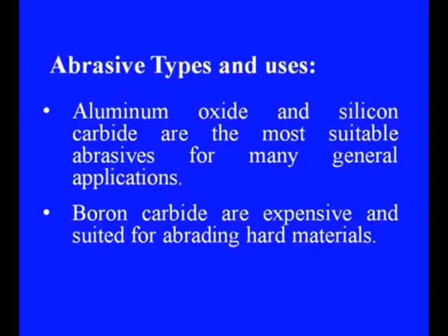The most widely used carrier is a high viscosity rheopectic fluid. At any constant rate of shear, its apparent viscosity increases with time to some maximum value. The base material has enough degree of cohesion and tenacity to drag the abrasive grains along with it through various passages or regions. Then what are the different abrasives used in this particular process?